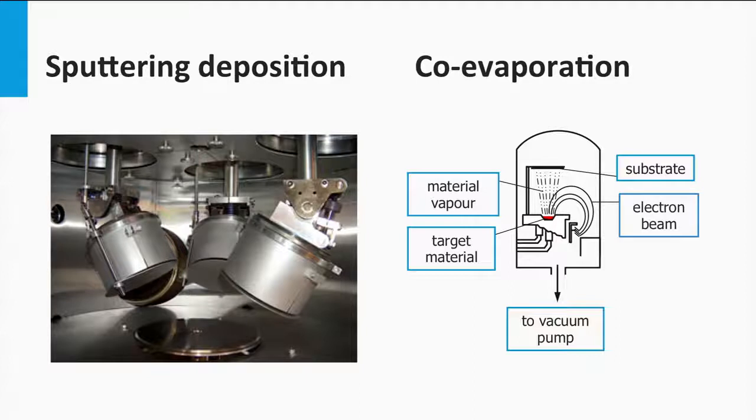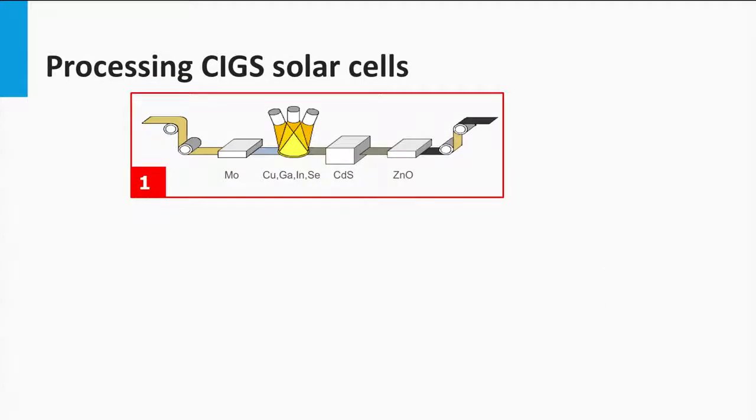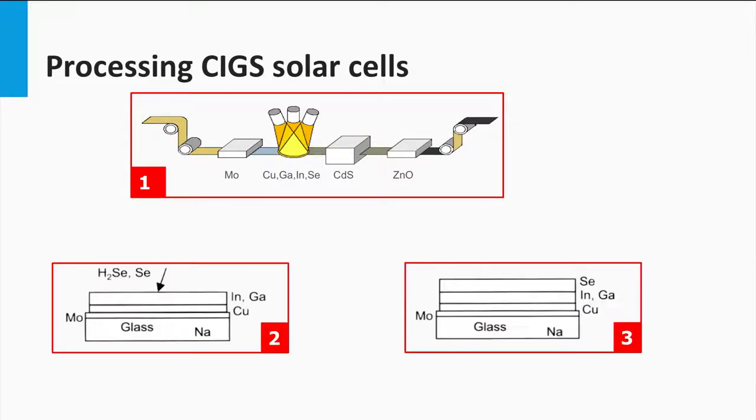Two approaches can be used. First is the sputtering and co-evaporation on a substrate at high temperatures. During the process, there is an additional selenium source. During deposition, a CIGS film is formed. The second approach is sputtering and co-evaporation on a substrate at room temperature. The deposited films on the cold substrate are thermally annealed in presence of a selenide vapor to form the final CIGS structure. Another option is to deposit a selenium-rich layer on top of the initial deposited alloy, and this is